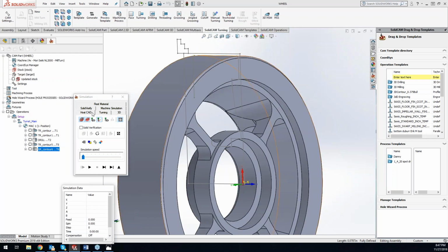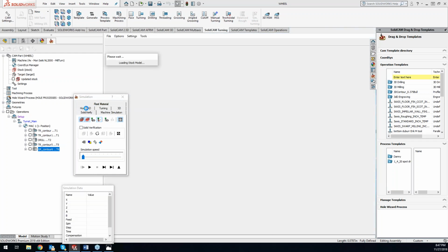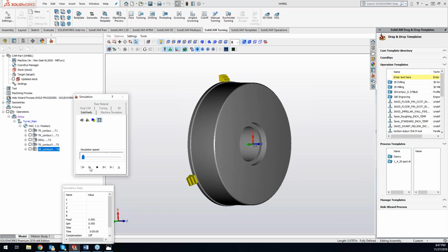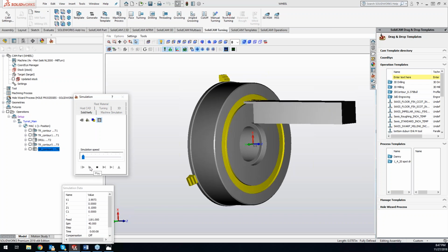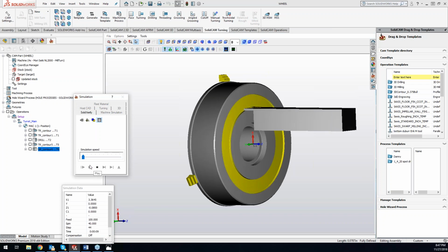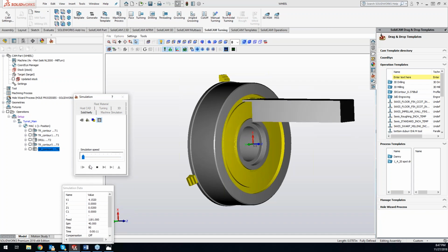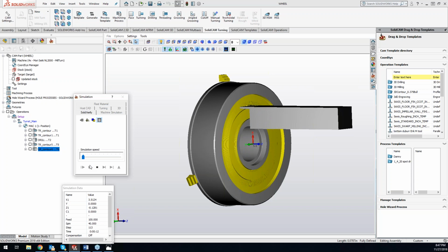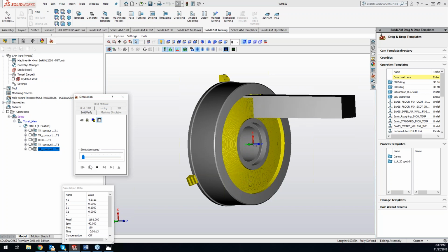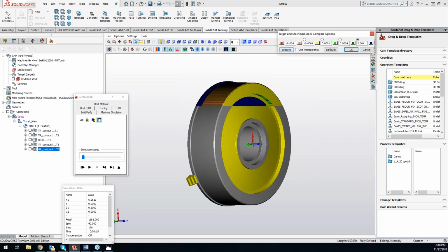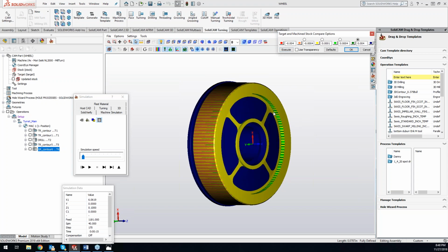All right, let's see what we have here. I didn't set up too many of the parameters. I just left it at the default, so it's stepping over 40 thou each time. And we should be doing a finish pass once it's done here. So we got a nice smooth finish pass. And as a sanity check, let's make sure, yep, we're right on that yellow green all the way through.